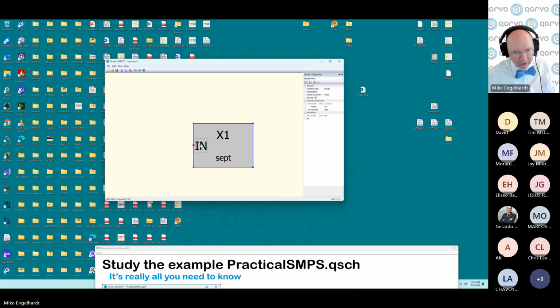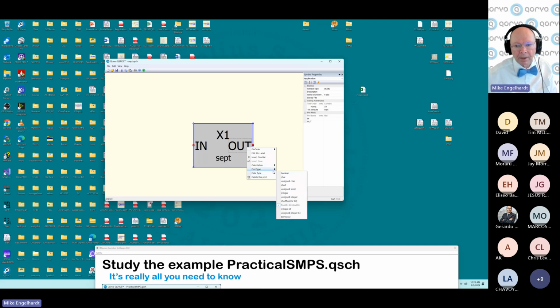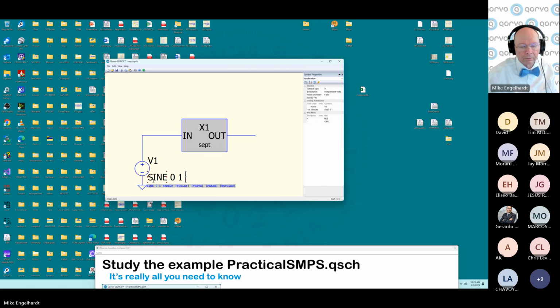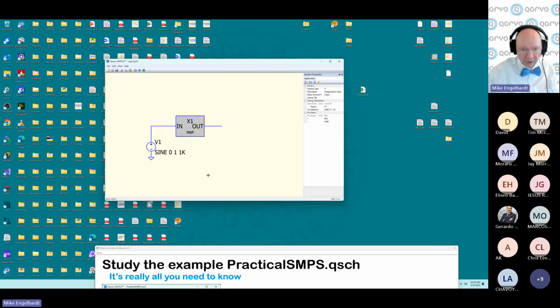All right. Now I want an output. Control C, Control V, Control E mirrors. Let's change the name to out. And now the port type, instead of being an input, I'm going to make it an output. The data type was copied as float, so that's all good. Okay. Now I want to write the C code. Well, actually, I'll hook up a test vector first. I'll put in a sine wave. And I'll start with a simulation command.